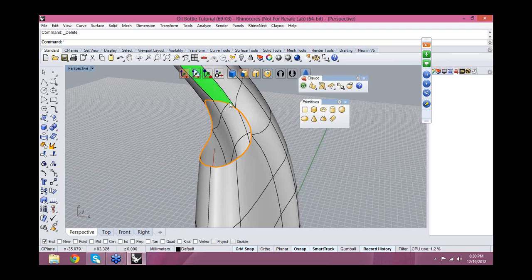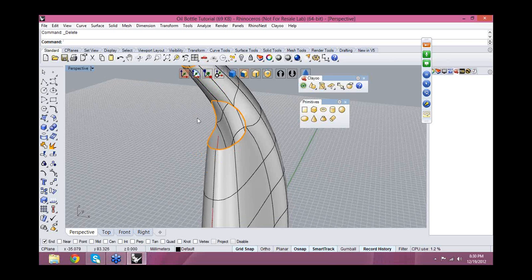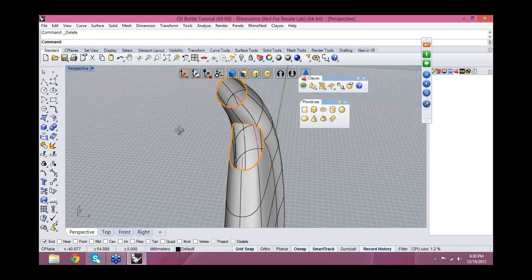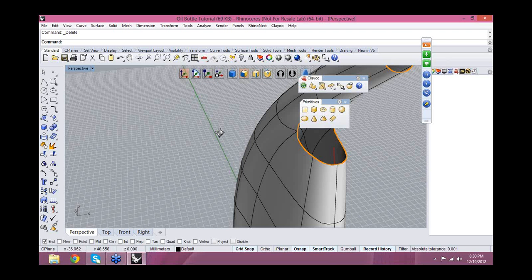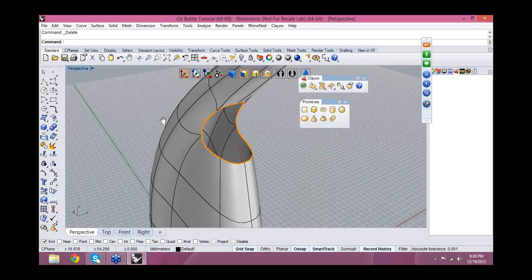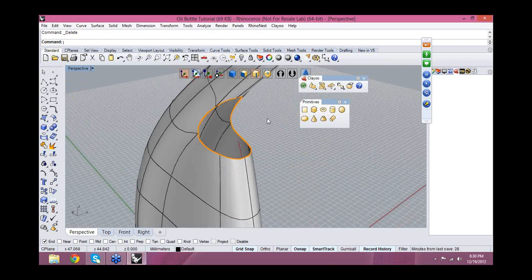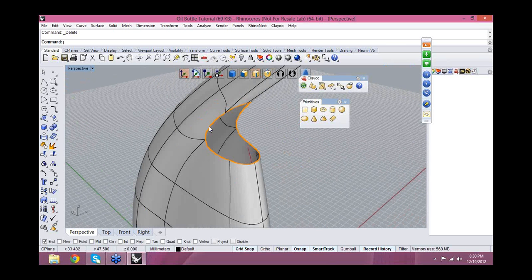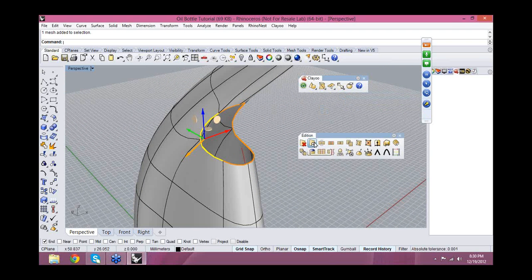It's not a problem, but it's easy to identify if you have different colors, okay? Great. Then the next step is we will fill that, okay? We select edges, and we will select this edge and this edge. And here in addition, we have an option to add face, okay? And now we will select this one, and this one, and add face, okay?